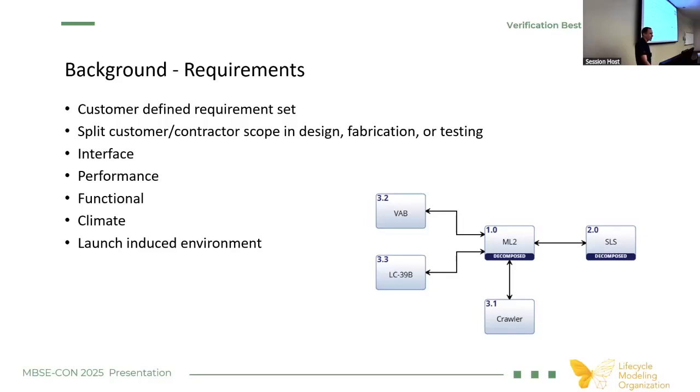So those launch-induced environments are considered for a lot of what's actually happening and how you're going to show that you actually can meet those performance requirements and hopefully not fail up until the point where the rocket leaves. Now, one of the fun things about this is the launch-induced environments that were incorporated at the beginning of the project. Eventually, when they launched that Artemis 1 mission, they did have to go through and actually update all those environments. So after the structure was designed, they had to go through and reanalyze and reassess it to show that the higher actual loads would actually be survivable.